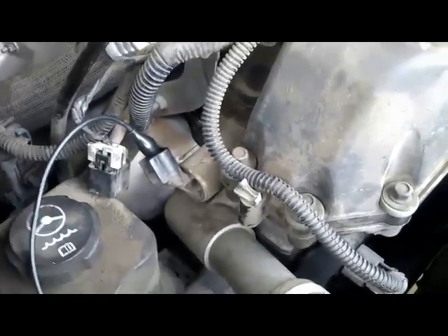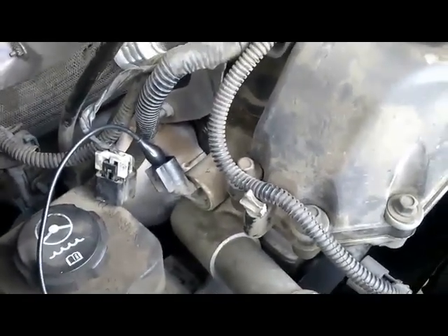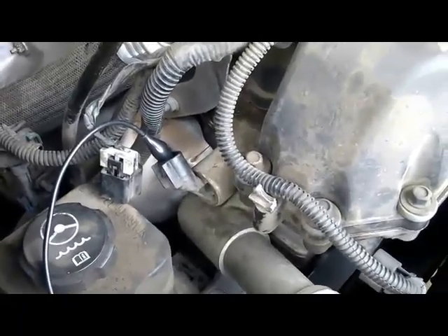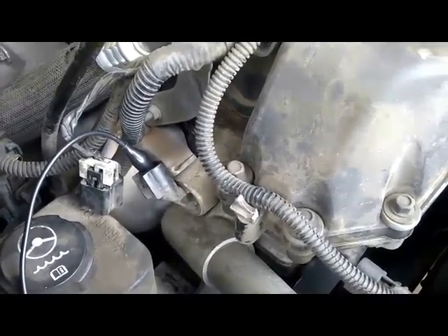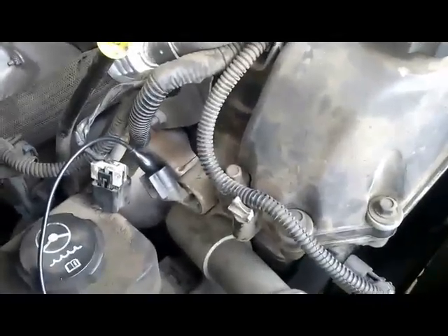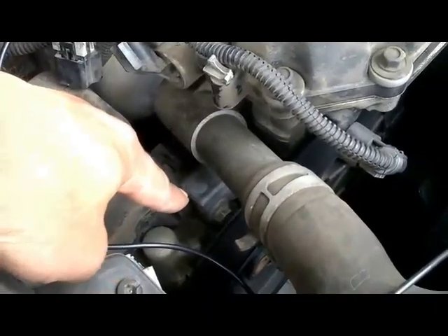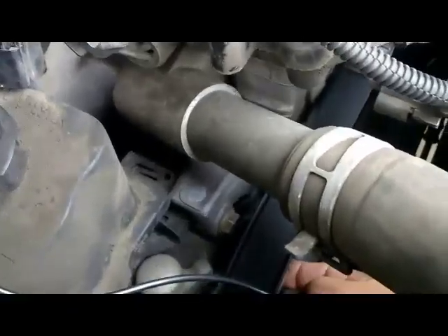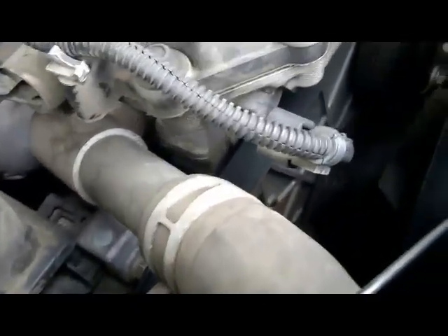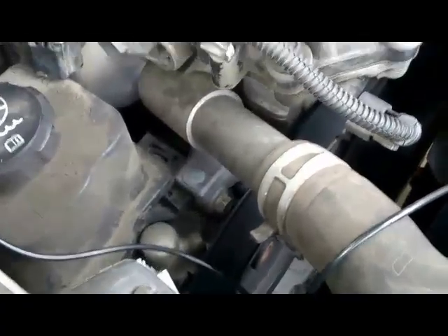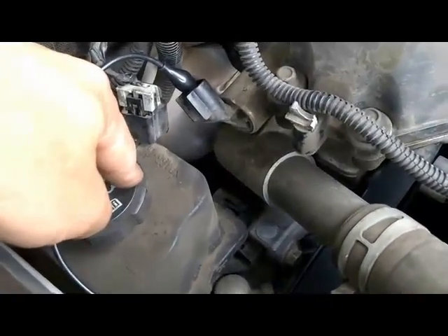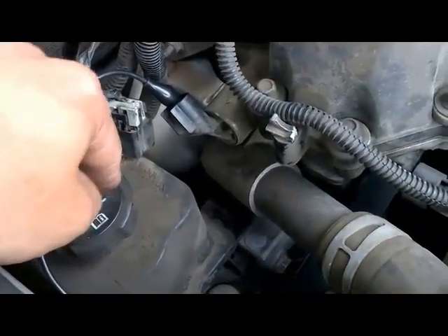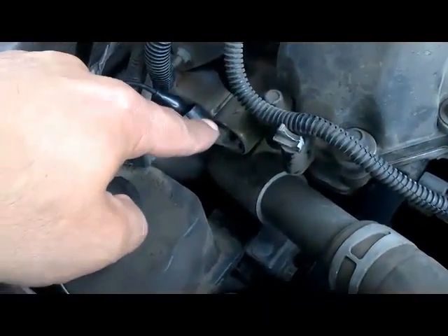So I guess our last thing to do is to confirm this solenoid by doing a visual inspection by removing it from its housing, and see if the screens are maybe clogged up or maybe broken. So here we go, guys. Next is to remove this solenoid, and to remove it, you have to remove the 3 bolts that hold your power steering pump, which are located somewhere right here. That's one right there, and the other one's on the other side, and the third one will be beneath the pulley. So it has 3 bolts. Without this reservoir being moved back at least a couple inches, this solenoid will not come out.